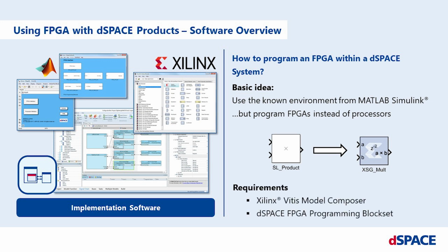As a second tool, we use the Vitis Model Composer from the FPGA specialist Xilinx, which brings us specific Simulink blocks for creating FPGA designs. This tool will be running in the background. We simply make use of this technology. The third component is the DSpace FPGA programming block set, which takes over control, ensures proper interaction of the tools, and allows easy access to I/O resources. As a last step, Configuration Desk is then used for combining the FPGA application with the process application, before ControlDesk provides an easy and comfortable way for monitoring and, if needed, for debugging.